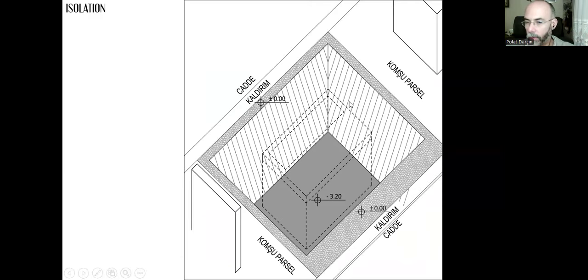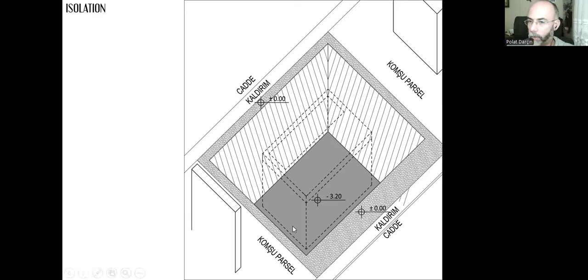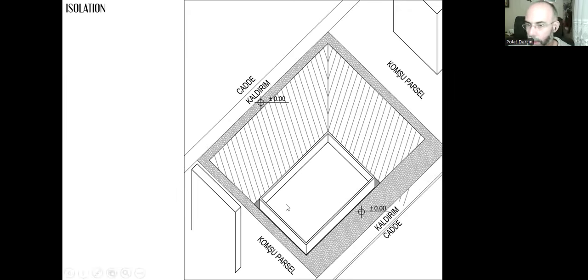In order to do the construction of the foundations, the basement floor, first we need to excavate the area and there will be just earth, damp earth, and it will be hard for the workers to work on that mud. So we can have concrete, only 10 centimeters without the reinforcement bars, and we can have these sides raised like 50 centimeters.